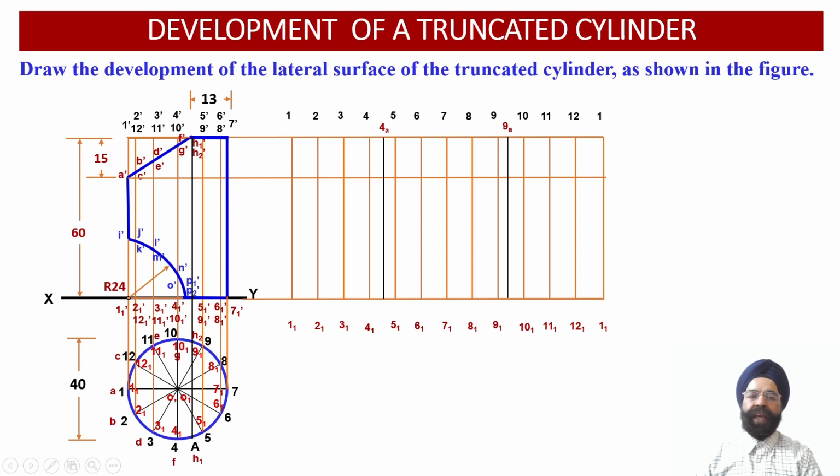So now we know that the first point of intersection of this AIP happens to lie onto the vertical generator 1 dash and 1 1 dash over here. Points A, 1 and 1 1 coincided with each other in the top view projections over here. So now once we draw a horizontal projector line through point A dash, let us evaluate the intersection of this horizontal line with vertical projector 1 and 1 1 over here. So one point of intersection will be obtained over here corresponding to point A. Another point of intersection we are going to obtain over here onto the vertical generator 1 1 over here.